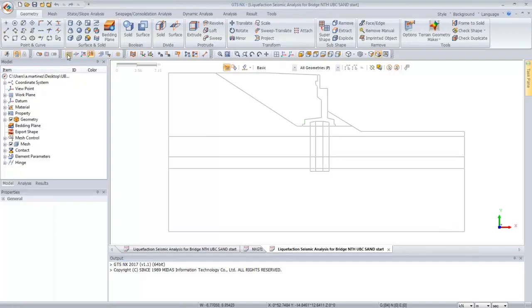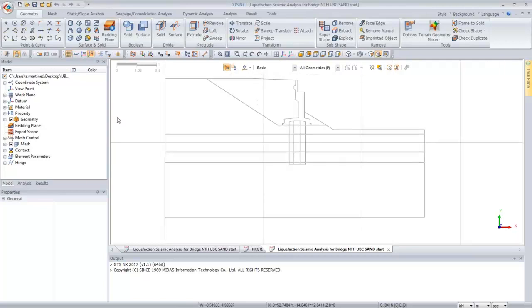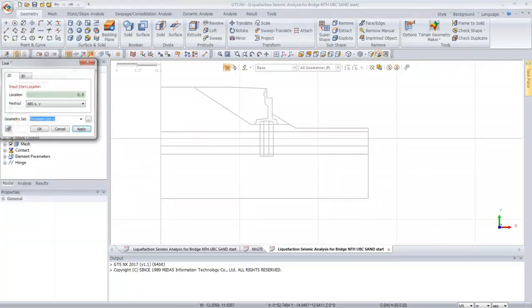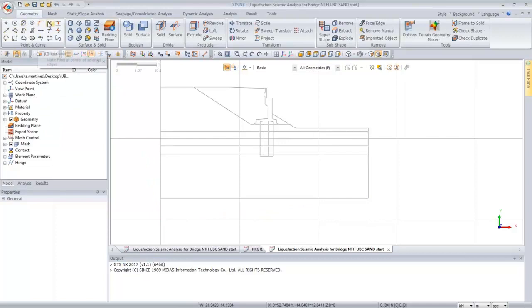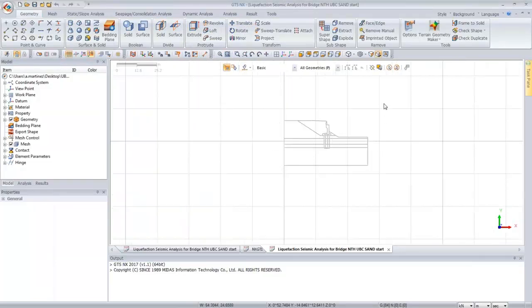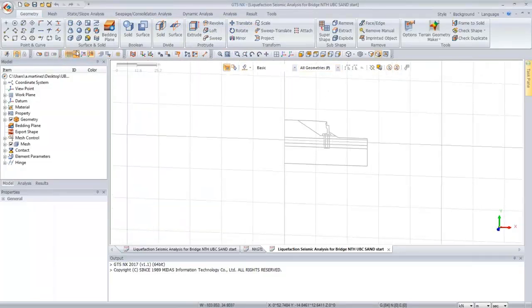But if I wanted to modify it, add new things to it, I can activate this grid, which would allow me to draw directly on it any kind of new geometry. And similar to AutoCAD, I would use different commands to either extrude or modify or translate or rotate. I can also change the size dimensions of this grid, activate the origin, or different views all from here.